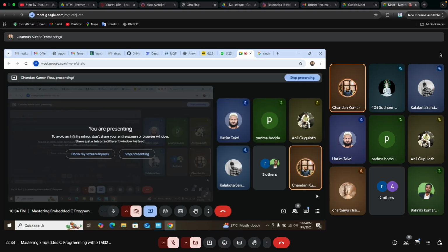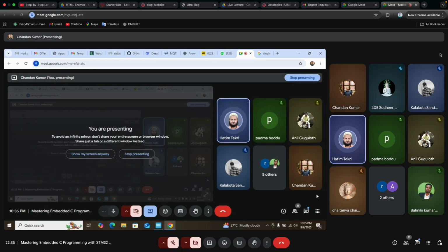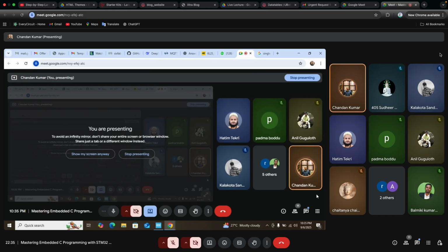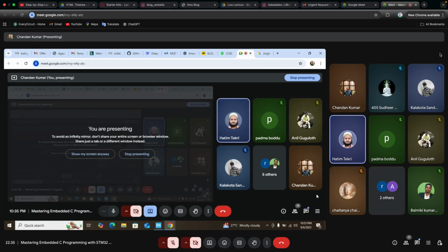Now the fourth data frame is acknowledge and not acknowledge. You can just write it as ACK or NACK. We will use the same ACK or NACK in the code. ACK stands for acknowledge and NACK stands for not acknowledged. So in the read-write bit, for read it is high or low? To read it will be 1 and to write it will be 0.